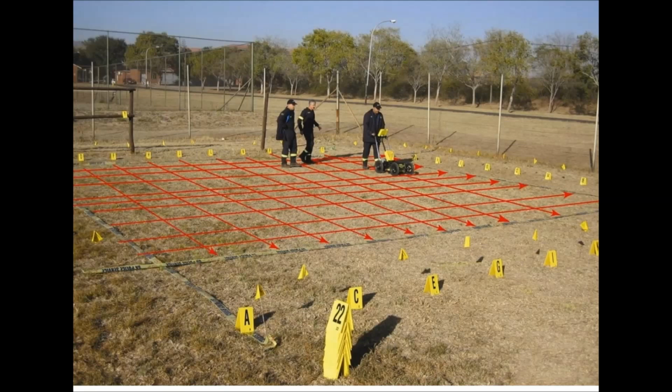The ability to see GPR responses as depth slices allows users to see the spatial relationship of subsurface targets. This can make interpretation much easier, as targets of interest are more easily differentiated from targets of no interest. For example, responses from utilities tend to produce linear targets, while local targets like a small piece of metal or an ancient artifact often appear as point targets. So utility locators are interested in linear targets, and forensic investigators and archaeologists might be interested in point targets. Depth slices provide this information faster and better than any other method.